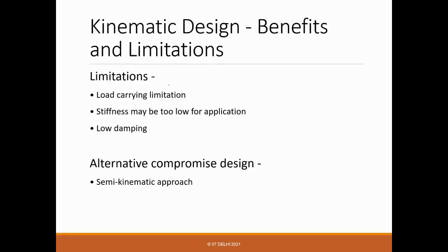Load carrying limitations will be there because you are not using the entire surface, but limiting to functional points, which can be just a contact point. If you use point contact in machine design, you know stresses will develop and there will be failure. So the load capacity and stiffness can be very low for the same reason. Low damping, again the same reason, because you are limited to localized contacts, not contacts over a large area.